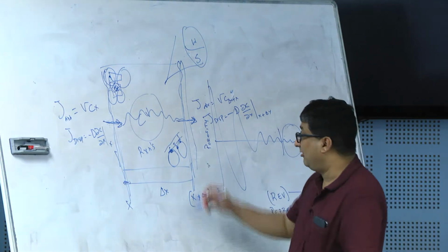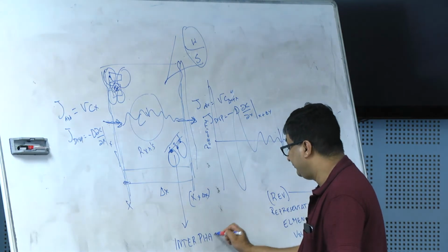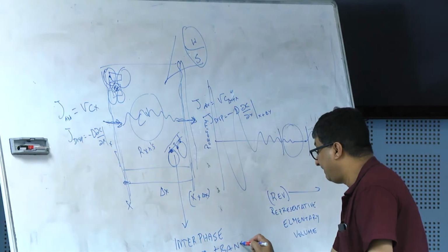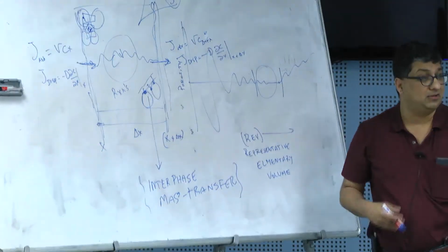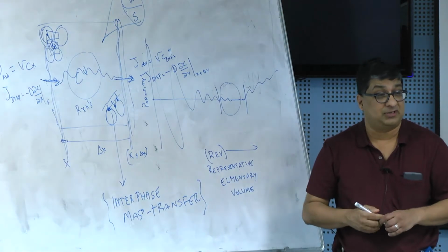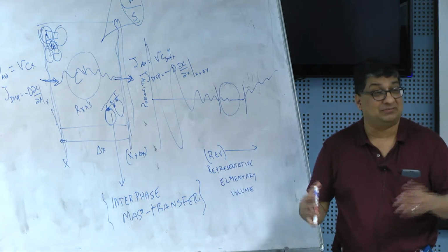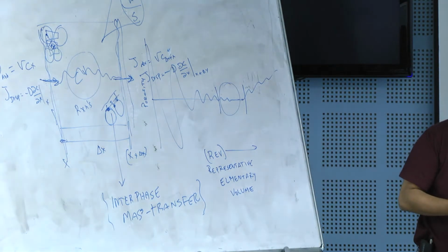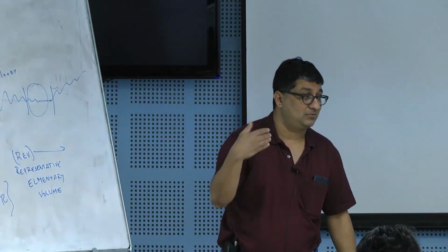We call this interface mass transfer, or partitioning; soil water partitioning or sediment water partitioning is one other common way to say it. But they both are reactions in some sense. One is a phase change reaction. We are taking a chemical, we are not changing its constituents or composition, we are just taking it from one phase to another. The most common groundwater interface mass transfer is a chemical going from the liquid phase to a solid phase.